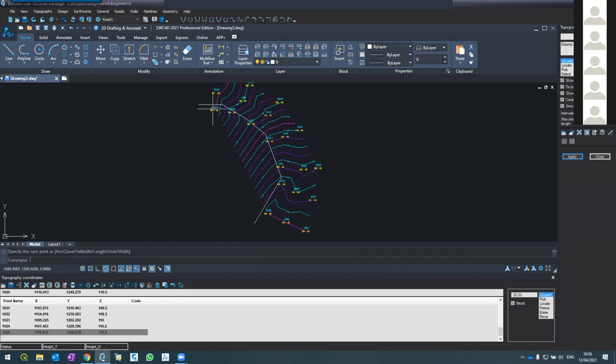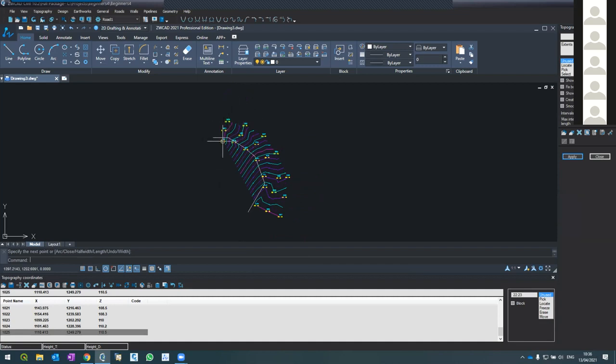So the software did an interpolation between this point and this point, and this point and this point, although the interpolation should stop here. We call this the border problem. In fact, the software will always go to something that we call the convex hull, meaning always look for the maximum area of coverage.